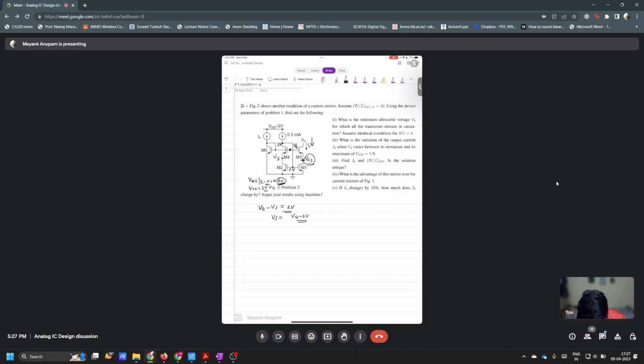Sir, VDS equals VGS minus VT, no, sir? That is for the transistor to remain at the edge of saturation. Sir, VGS will be constant, no, sir? Then VD equals VG minus VT. So VT will actually be independent of VGS, no, sir?